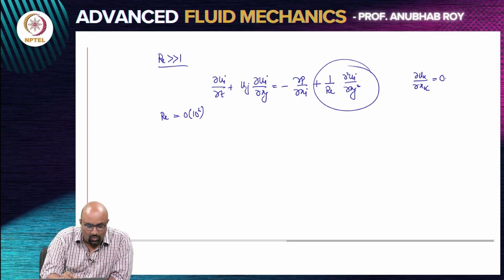And that is basically what we ended up doing in a lot of the potential flow calculation. So, we realize that by saying that Reynolds is very large, where you are looking at high speed flows, we are making the assumption of dropping the viscous forces. And by dropping the viscous forces, we arrive at a final conclusion that the object can move with any velocity in the fluid and experience no resistance.